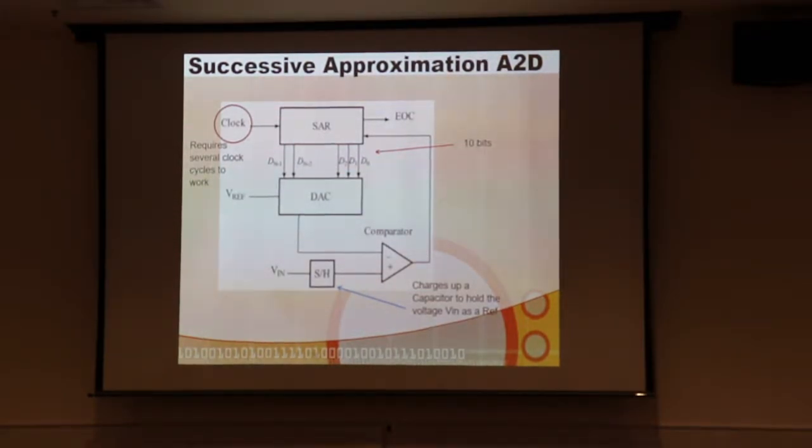Let's say you're sampling it pretty much at 1,000 hertz, but there's kind of a little warble on that 1,000 hertz, so that sometimes you're sampling 998 hertz and then 1,002 hertz. Well, then you're actually modulating the signal you're trying to capture with this jitter signal. So you have to subtract that off or somehow deal with that.